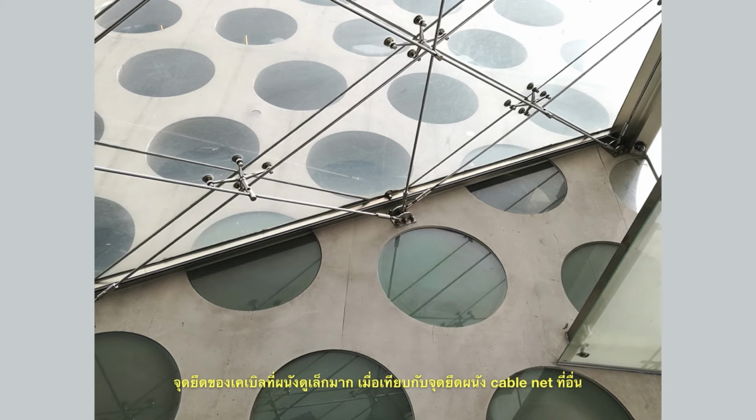And the fixing of this anchor point doesn't look sufficient for anchor point of the cable net system, so I don't think that the cable is tensioned properly to the requirement of the cable net system. By the way, the detailing and craftsmanship of the fitting and accessories are very nice. However, this won't help in terms of structure.